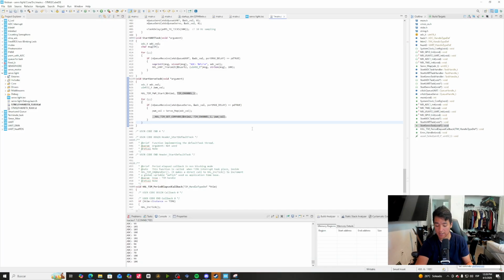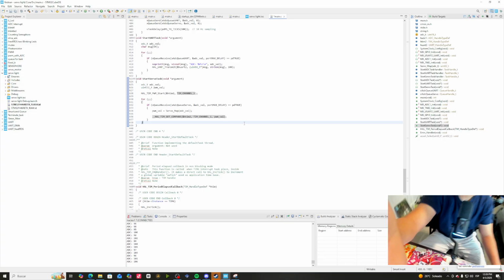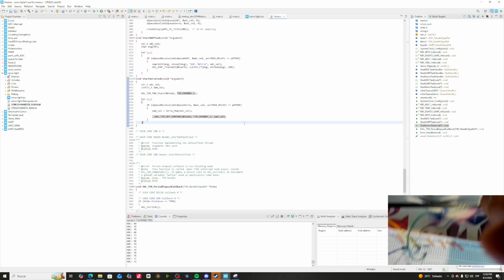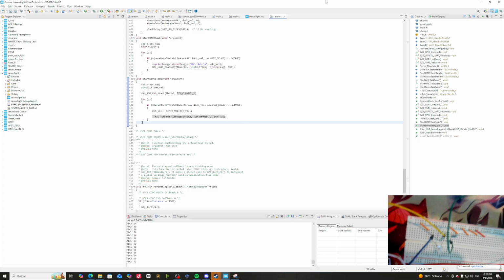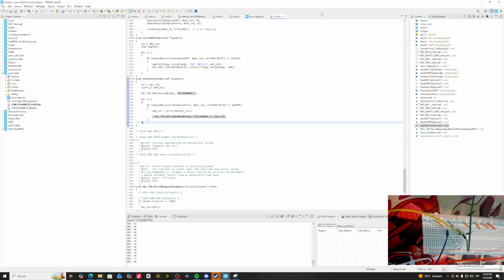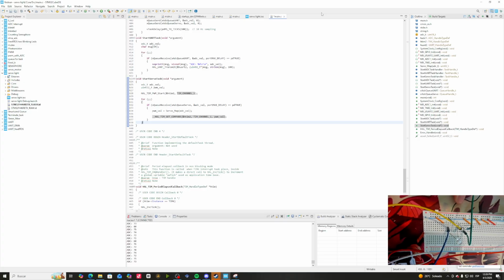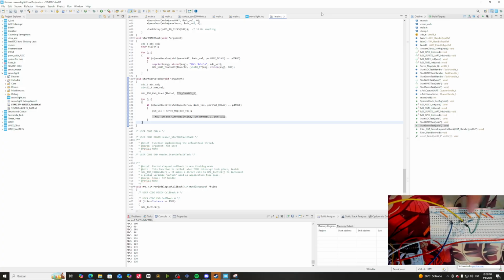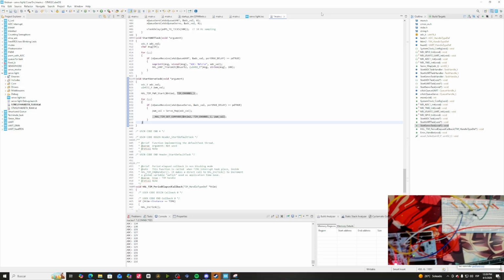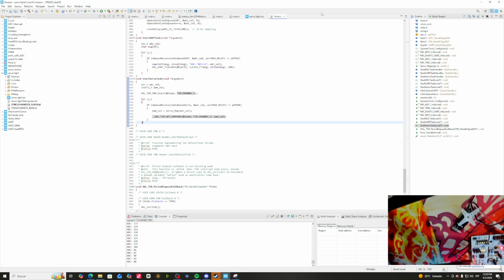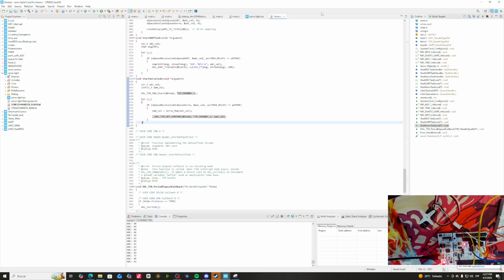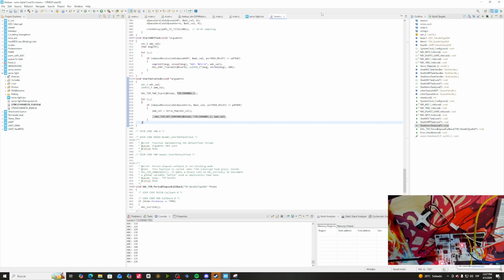I already have it running right now. So I'm just going to take the camera and show how it's working. Then we have here the connections correctly connected. We have the phototransistor connected correctly to the resistor, then connected to our board, and then we have our servo motor right here, connected with the PWM pin, to the ground and also to 5 volts.